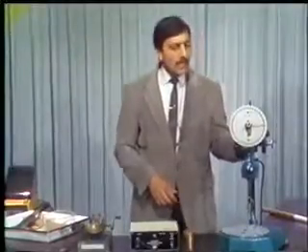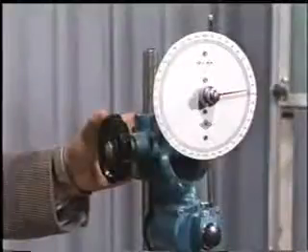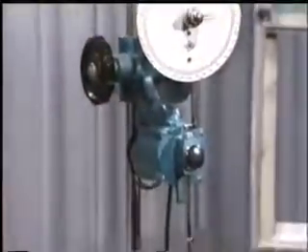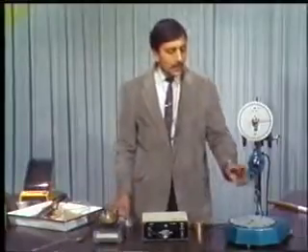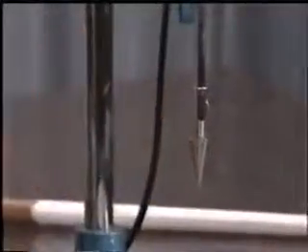The determination of liquid limit by the cone penetrometer also has been standardized by Bureau of Indian Standard, and detailed specifications have been laid down. This method has a few advantages, because whereas in the liquid limit device method it is difficult to find out the liquid limit of the soils which contain appreciable amounts of sands, with cone penetration it is simpler to determine.